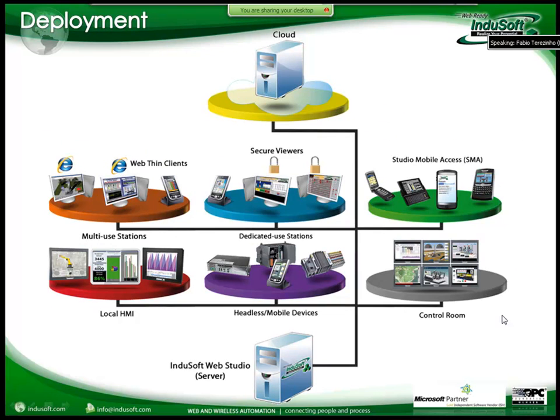So from the deployment point of view, you can create the application within InduSoft Web Studio and then deploy it to embedded devices, local HMIs or regular PCs, or even to the cloud. And then visualize the information from web thin clients using Internet Explorer, where you can visualize all the screens, all the graphical interfaces. Secure Viewer, which is a thin client as well, but instead of using Internet Explorer, you install the InduSoft thin client host called Secure Viewer, and it displays the application in full screen mode.